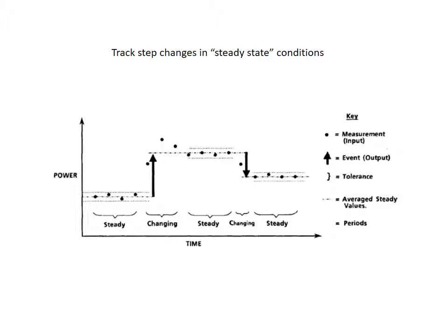And so what an event-based algorithm for non-intrusive load monitoring does is it looks for discrete on and off points or jumps from low to medium to high. And so what that means is what we call step changes in power consumption. So the step changes here that are pictured are represented by these black arrows. And the first one, you see there's a sort of steady state power consumption, and then you see this increase from one period to the next